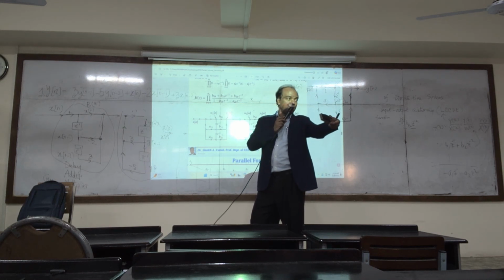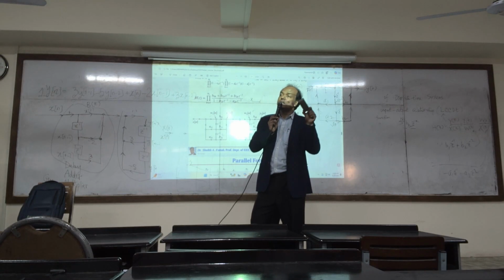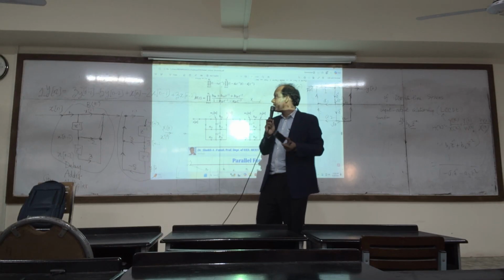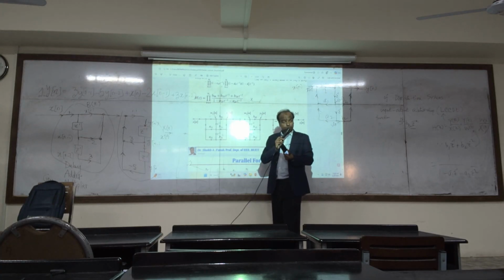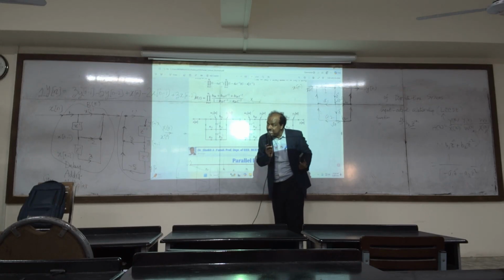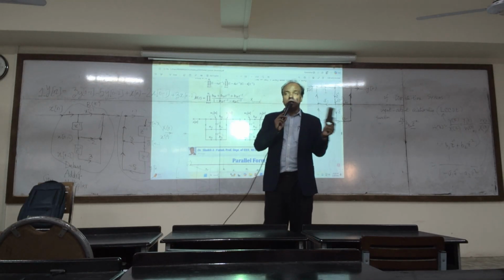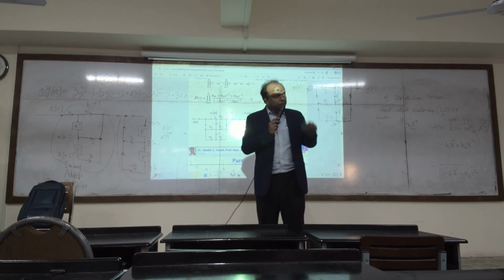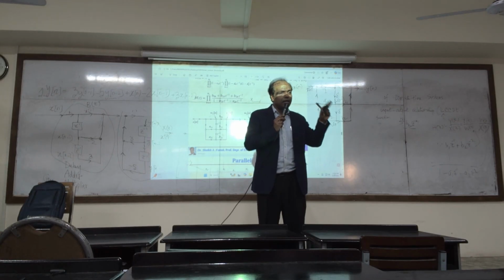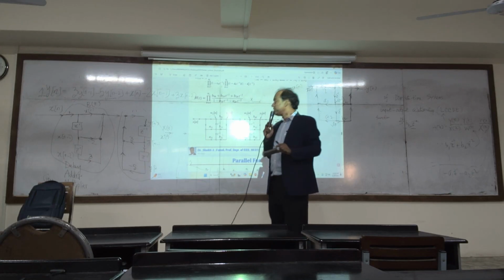Before partial fraction, terms are multiplied. After partial fraction, terms will be added. The same concept we can do here. For example, if the order is 8, I can do the factorization and then the partial fraction, and from the partial fraction result I can say how many second order sections will be added.